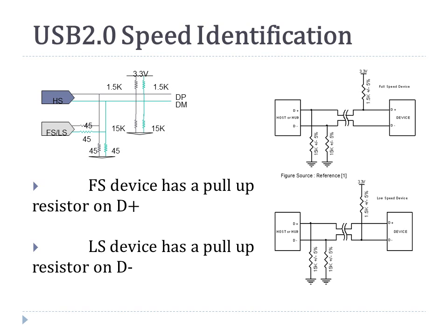on their data lines. The full speed device has a pull-up on the D plus line. So when a full speed device gets connected, the D plus line is pulled high to 3.3 volts, and the host detects this 3.3 volts on the D plus line to infer that a full speed device has been connected. Similarly, a low speed device has a pull-up on the D minus line. So when a low speed device gets connected, the host monitors the D minus line and finds out that it has been pulled up to 3.3 volts and infers that a low speed device has been connected.